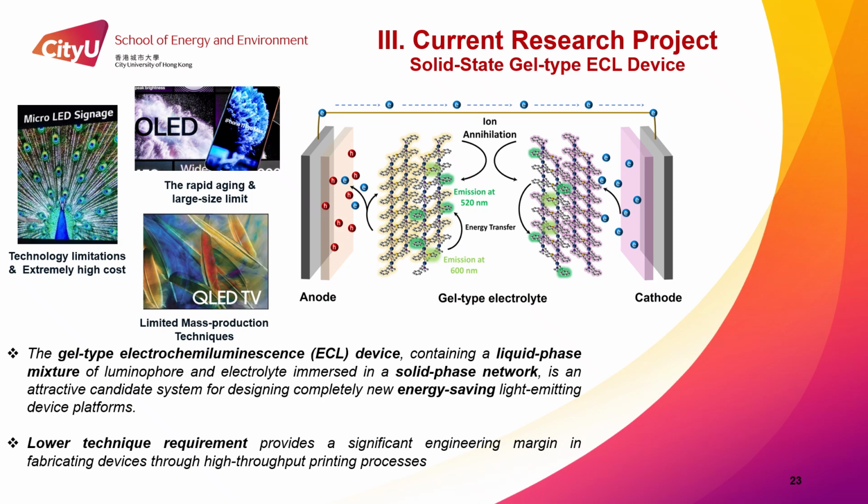For the third current research project, currently there are some issues for the fourth generation light emitting diodes. For example, rapid aging and the burning phenomenon in OLED devices, mass transfer and high cost in micro LEDs, high preparation temperature, and difficulty being compatible with large-scale roll-to-roll processes in QLED devices.